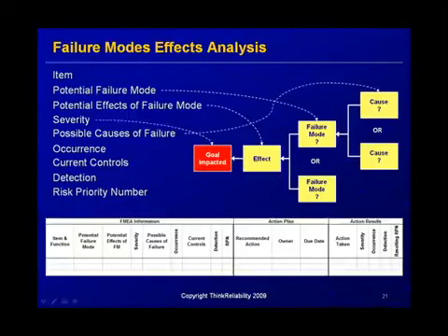The severity is the impact of the goals, and then the possible cause of the failure over here. So you notice the FMEA lays it out in an order that fits the FMEA organization for severity, occurrence, and detection to multiply out RPN. But if you laid it out visually, it creates this map, and cause and effect would organize them this way. So we like the worksheet that's used for an FMEA, and a cause map tends to really complement that.